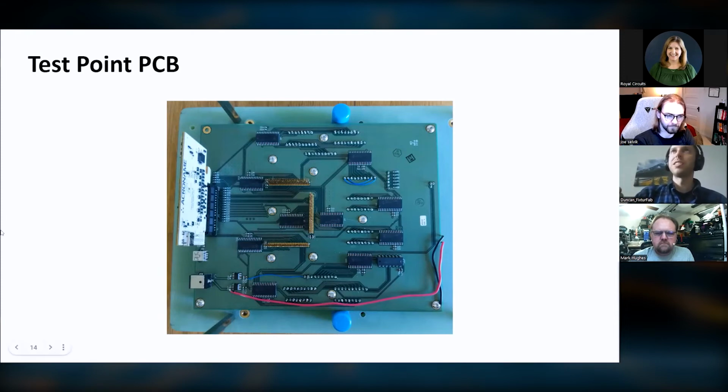To do the resistance measurement, you can get a DMM with a multiplexer built into it, and then you can just hook that directly up. Or with the acronym cards, you use a voltage divider setup where you use tri-state inputs to set one test point high and pull one test point low, and then you can measure the voltage between a couple resistors to figure out whether they're connected or not. Yeah, checking if a digital pin is connected by setting it high and low works, but measuring resistance is definitely the best way.